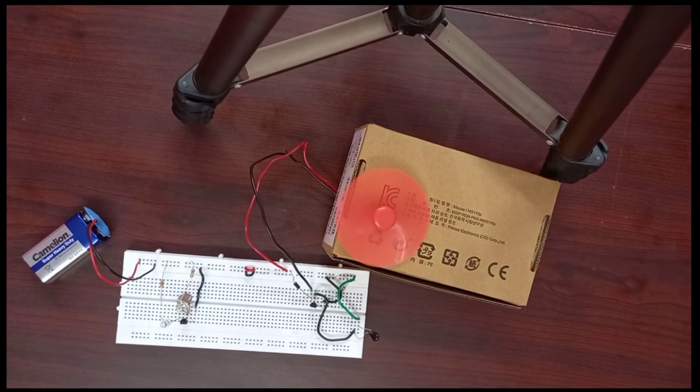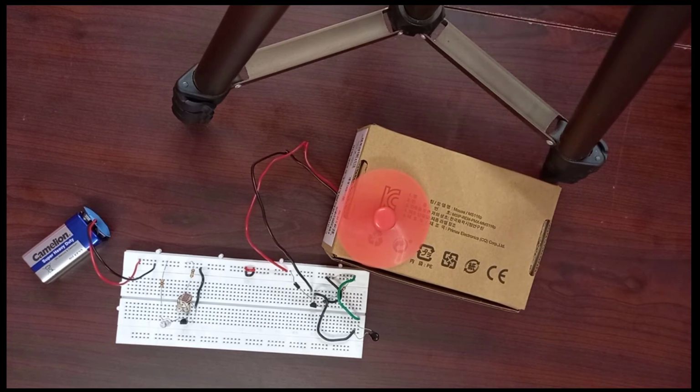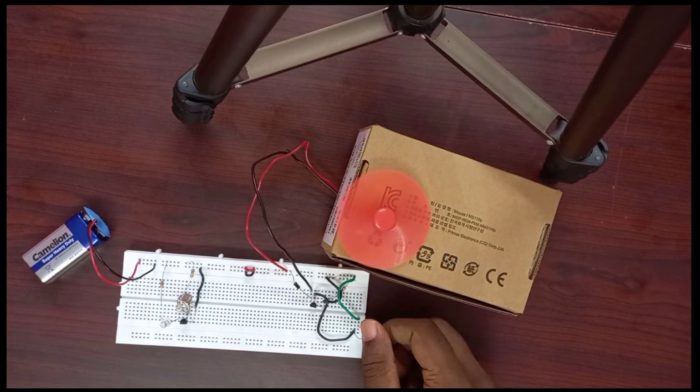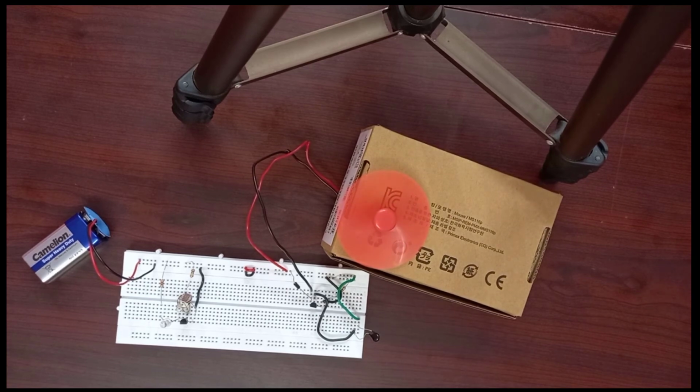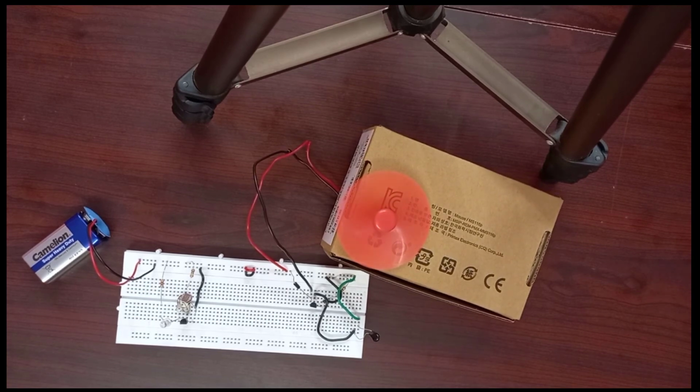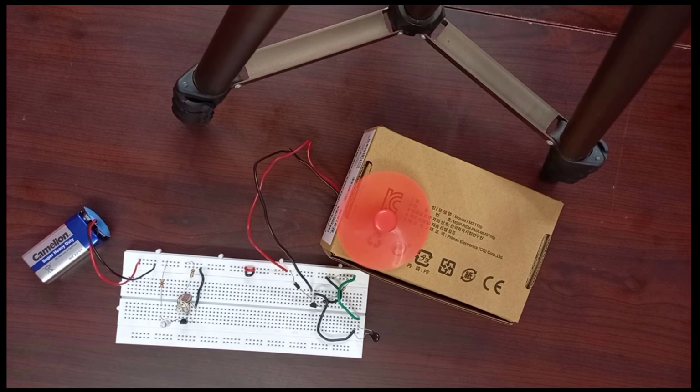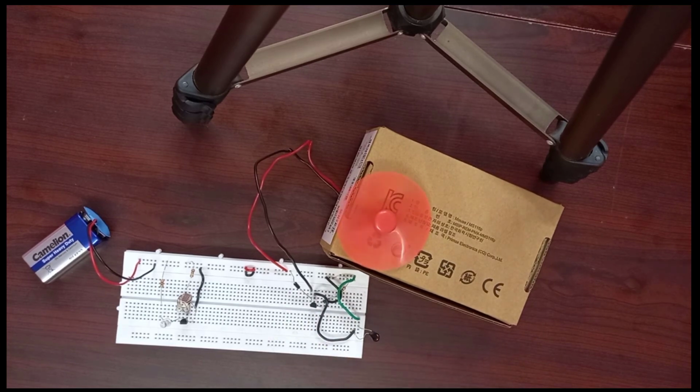When the temperature increases past a particular limit, the fan motor is automatically on. When the temperature level is reduced, it comes back to the normal state. The BC547 acts as a switch. All these units are mainly used for the signal conditioning circuit for the thermistor. Here I have used a low current operation. If we use a high current operation, then the selection of transistor, resistor, diode, each and every component is very important. Okay, thank you for watching.